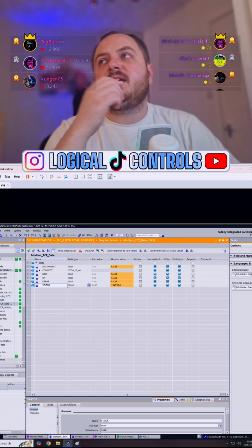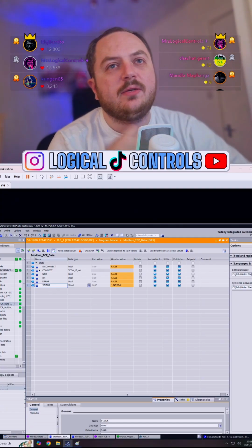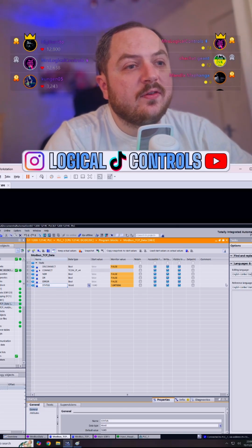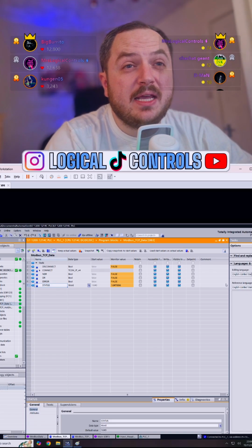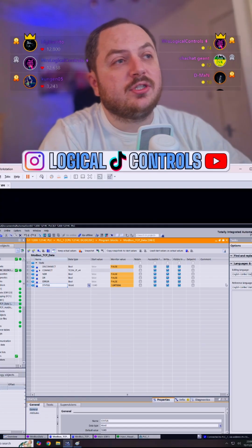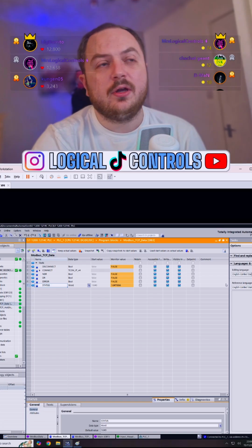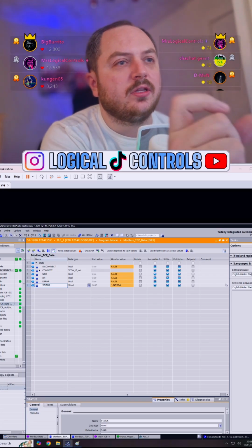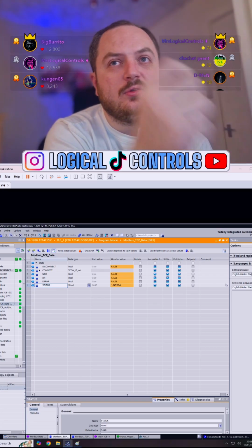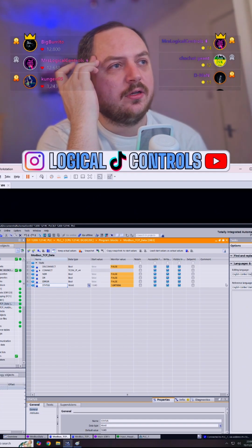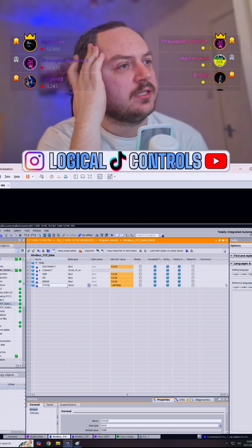Oh, I see what you're saying. It depends on how old the PLC was. I think with the FX5s and stuff, you definitely can. With FX2s, maybe even 3s, it was just never an option. You couldn't download the comments, or at least if your comments were longer than like 16 characters, you couldn't download them. Yeah, the older Mitsubishi stuff had some nightmares to it, Snarky Man, I'll be honest.